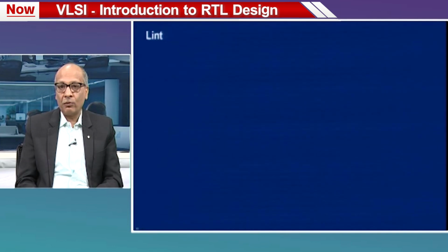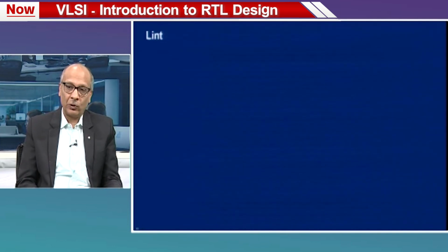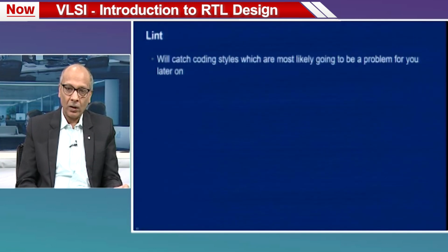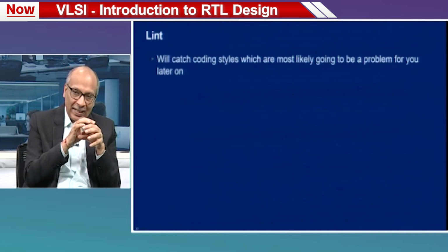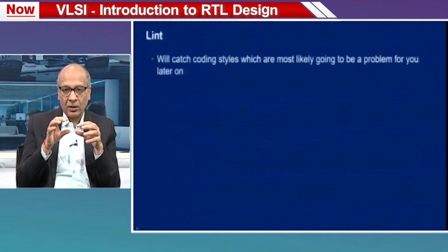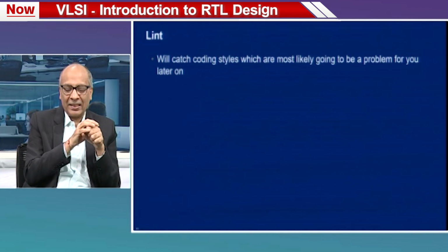So there are tools which do this kind of work. These tools are called lint tools or linter tools. So linter tools catch coding styles which seem to be reasonably okay, but will most likely create a problem at later design stages, right. So that is the idea of a linter tool, that it catches coding styles and code constructs which seem to be reasonably okay, but will create trouble later on for your design cycle.